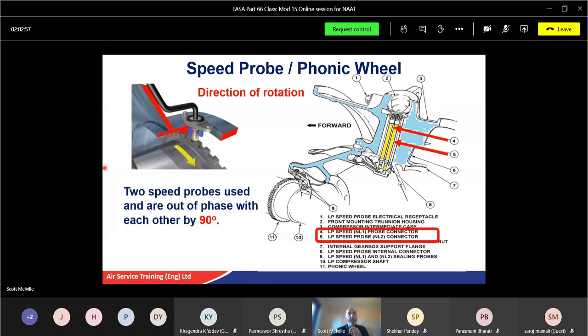Now, some aircraft will have a light that might flash to let you know you're starting, or won't come on at all. Well, it will come on if it's in the wrong rotation, going the wrong way. So again, your ignition system should not work until the engine is going the right way. Like the aircraft I was on, it just suddenly stopped. The starter motor basically went to start it, but because the engine's going the wrong way, it just stopped it spinning the wrong way, and it didn't even look right. I thought, oh, that's going to put a bit of damage.